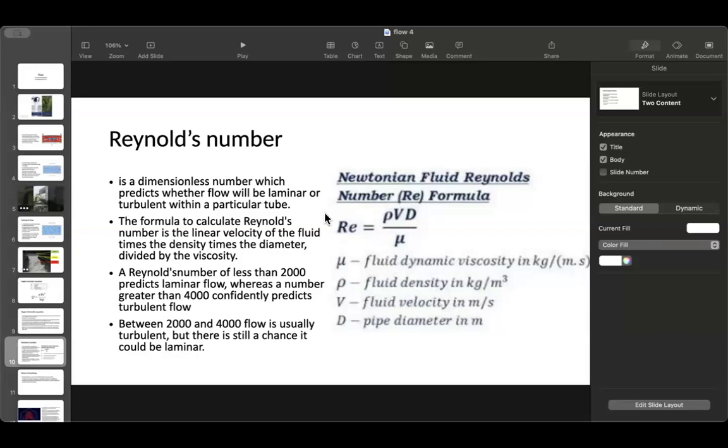Note that in the Reynolds number, we are using diameter, not radius. And note that here the factor with the greatest impact is density. I'm referring to density and viscosity multiple times because that's a question found in some books, and it helps to explain a very common example that I will describe now.